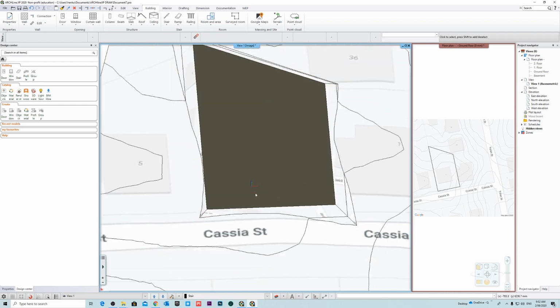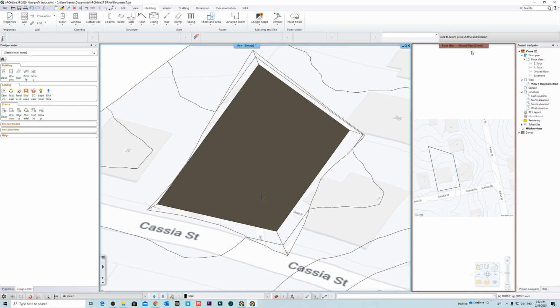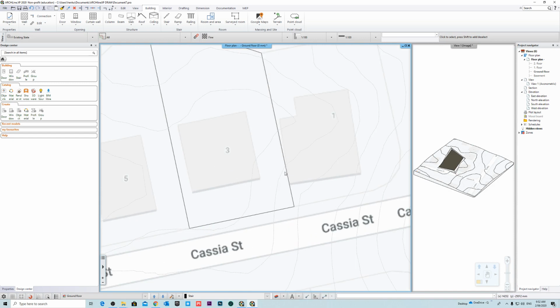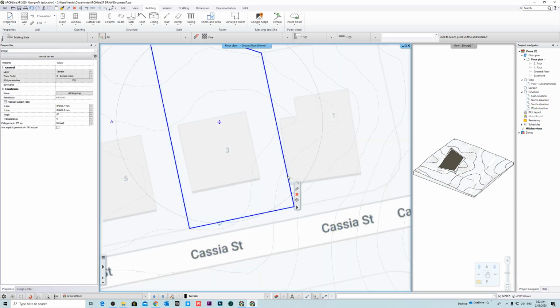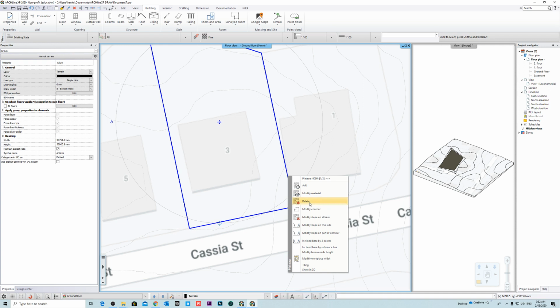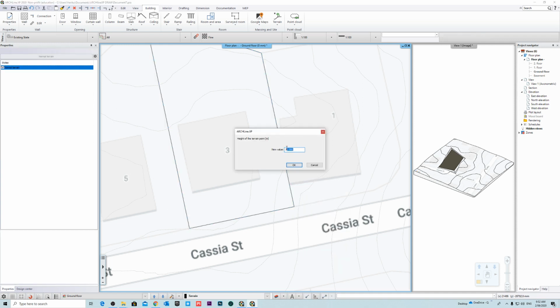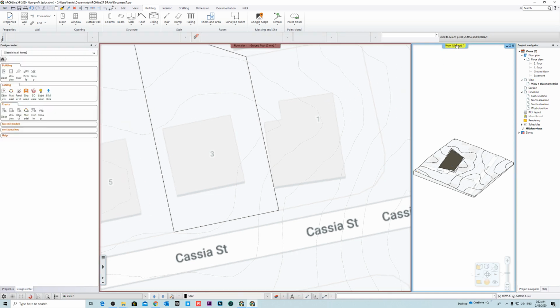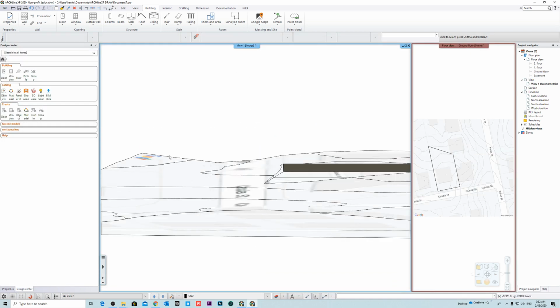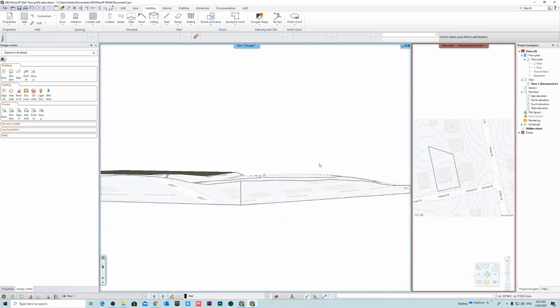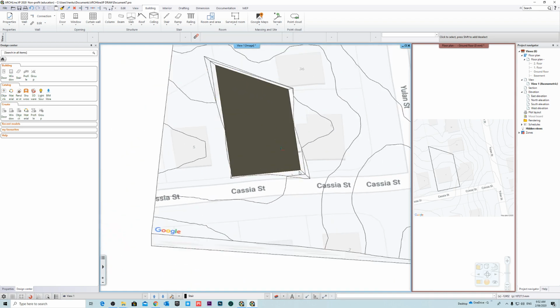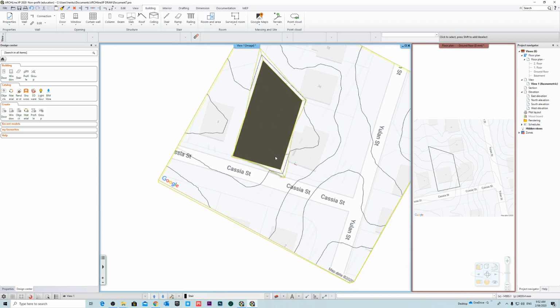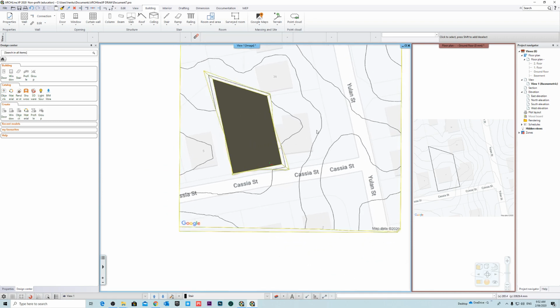So we'll just need to make some estimated adjustments. So we can just go back to it and we'll right click. We'll go modify terrain node height and we'll go 34.7. Right, go have a look again. Right, so that seems a little bit better. Right, now we can continue to do this for the surrounding plots.